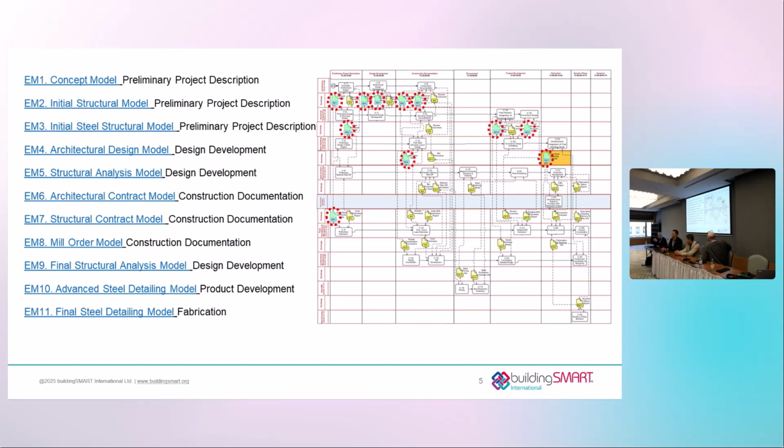So that's why we focused so hard on an MVD at the time that would allow for IFC files, one file type, to be able to be pulled and manage steel fabrication. It ended up being not probably quite as easy as we had hoped. We had kind of a custom extension of IFC. We saw not quite as much uptake from the industry as we had hoped. A few machinery manufacturers introduced translators. Software happened to be very cooperative, but you know, we had a little bit of a struggle.